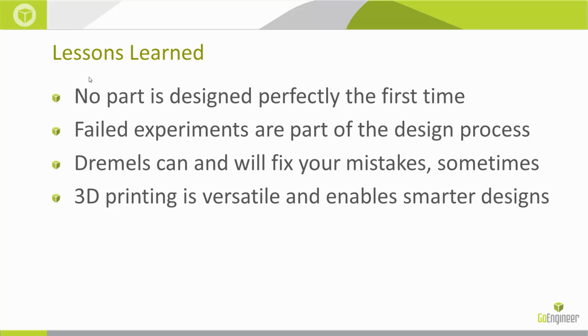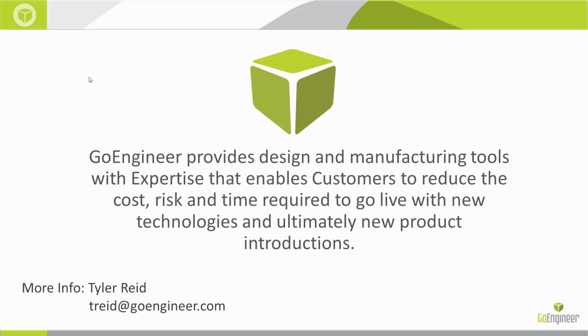And then also I learned that 3D printing is pretty versatile and enables smarter designs. It's versatile in the fact that I can print parts that go in the interior that look good, with a very smooth finish and very small features such as threads, or I can make parts that are durable enough to be mounted to an engine and run, and are going to withstand heat and chemicals. So 3D printing is something that people are becoming more apt to experiment with, but we've got a lot more experimentation ahead of us. So that about does it for this webinar, 3D printed car parts.